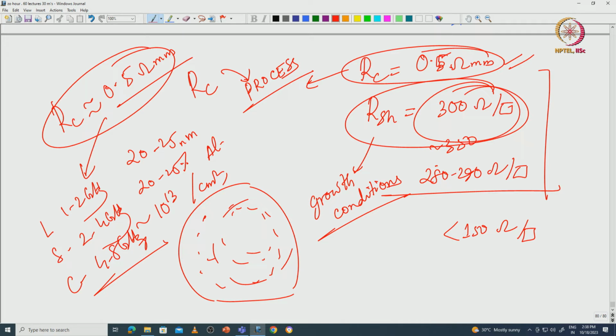of operation, or frequency at which you want the power, because with higher frequency operation your device is going to be shrunk, because your device dimensions will shrink. So your contact resistance may be the dominant factor that decides your delay. It could be the dominant parasitic factor, and you do not want the contact resistance to be the killer that defeats or kills your device.